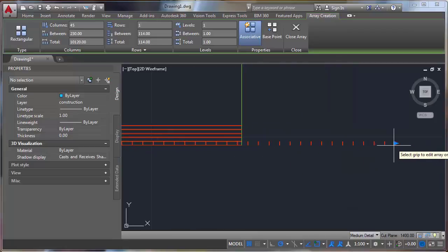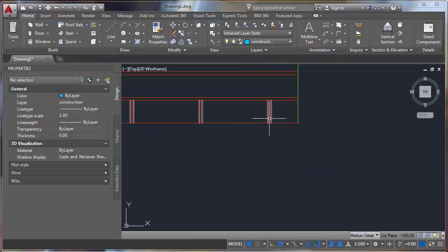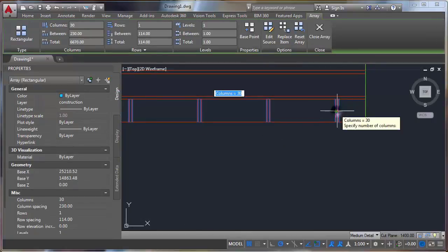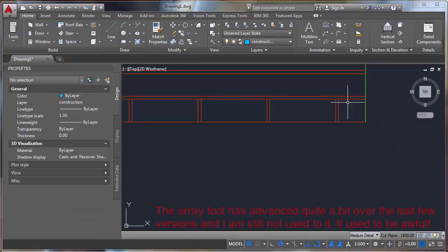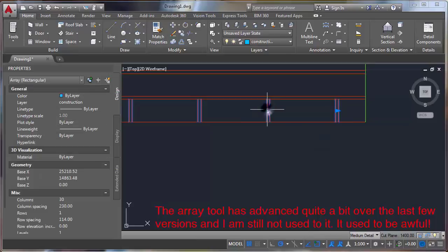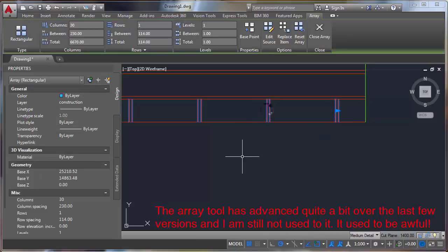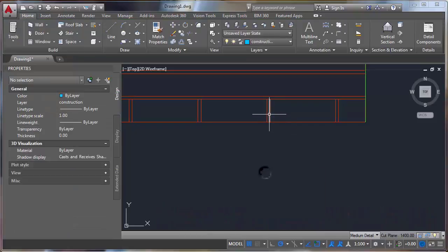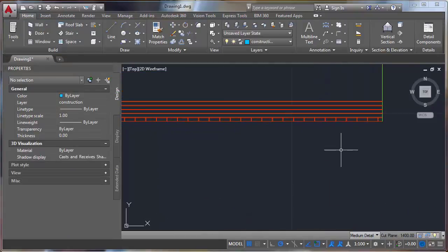Right. Come back here again. Just use that. Perfect. Nice thing also about AutoCAD is it remembers these, which means I can begin to change this. Sometimes that's annoying because you really just want access to those lines, so it's really easy to just select these and type explode. Explode will now turn these into individual lines, which is good.